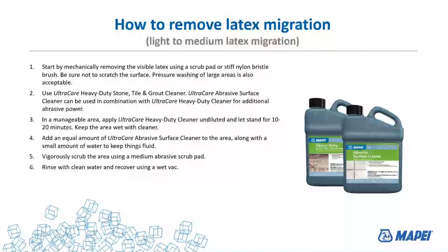I like to dry the areas with towels once I work. If you've got 10,000 feet, I treat it the same way as I would 1,000 feet, just one bite at a time. Once you rinse an area clean, I use a towel and dry it. I don't like an abundance of water just sitting around, potentially adding more problems, putting minerals back on the surface, letting it dry with water spots or something to that effect. I try to remove the water off the floor, to make sure that we don't have any other issues.